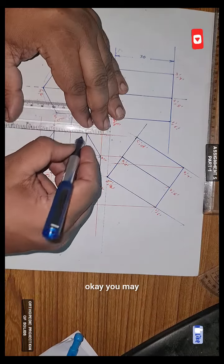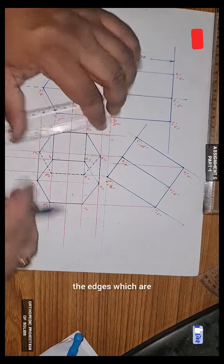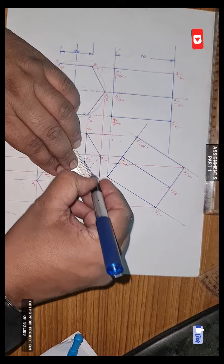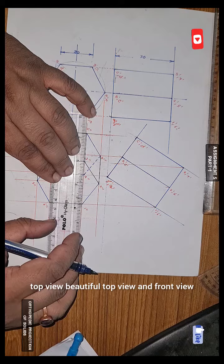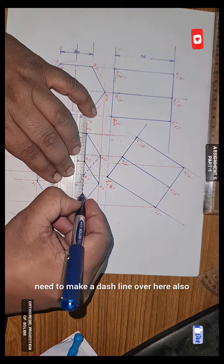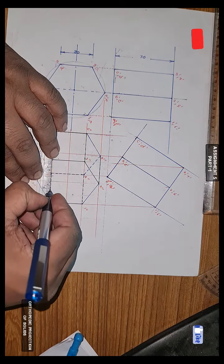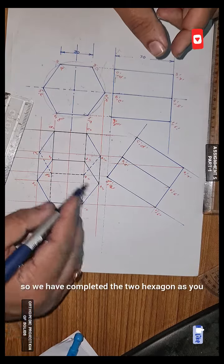Okay, you may have to dark the edges which are visible in the top view, and you will find a beautiful top view and front view of the diagram. Need to make a dash line over here also, because these edges are also not visible from the top. Make a dash line. Okay, so we have completed the two hexagon.